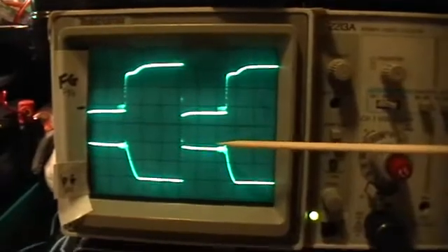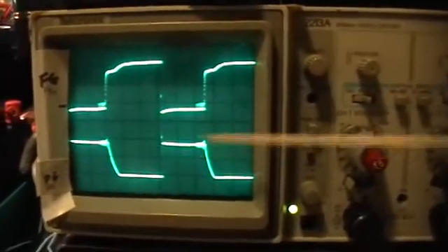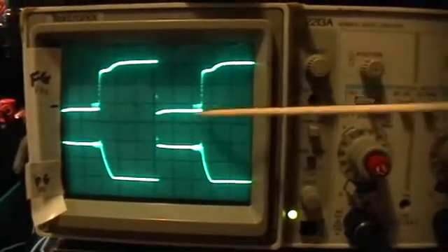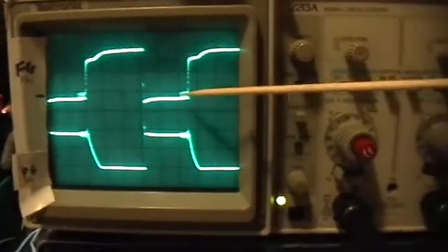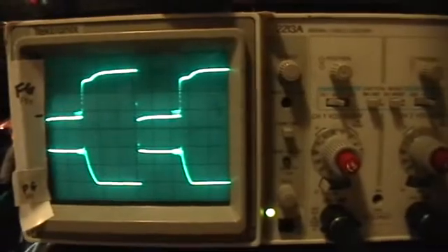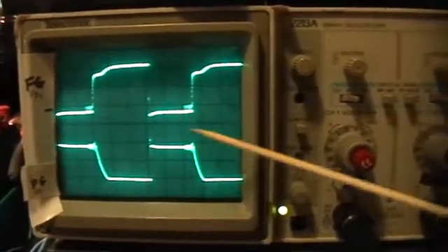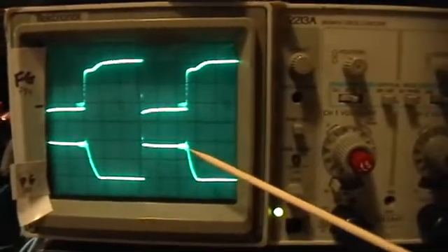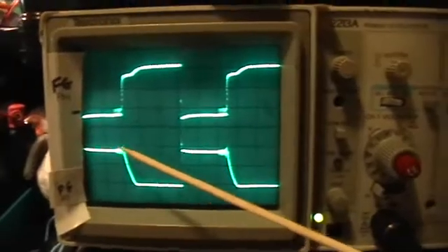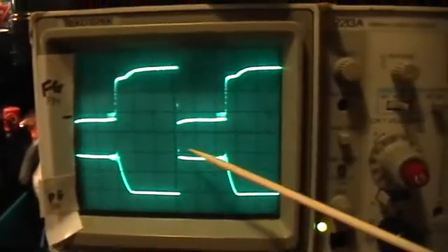Much of the time it actually causes the MOSFET to leak power when it should be cleanly turned off. And that parasitic oscillation is being driven by the weird oscillation coming from the 555 timer. Okay? So you've got to really be careful about these duty cycle issues and know what your MOSFET is actually doing to your load. The load is off when this signal is high. It's on when this signal is low, right?